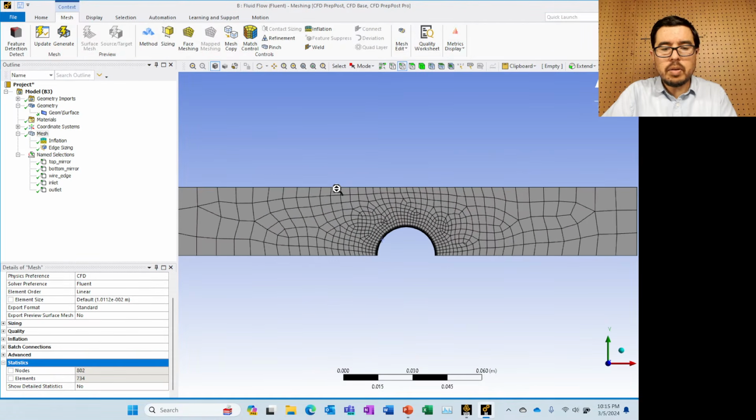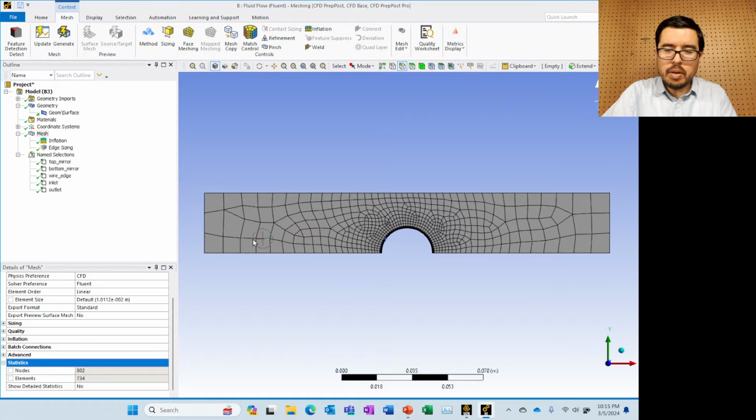Nonetheless, we come out a little bit further and we think, well, if the inlet's on the left, nothing really interesting is happening until I get to this region. So this might be sufficient. But after I hit this region, we saw backflow over a step. We see different effects that we might want to have a little more density over in this region.